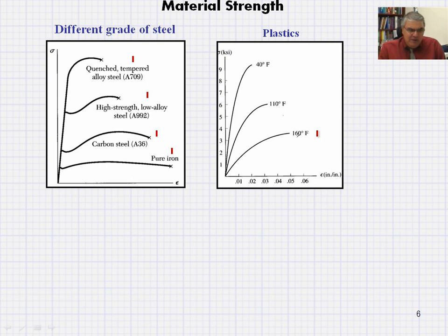So this last one down here, the strain is almost 1/3 of the one that's shown up here, but the strain is also 3 times or more. Again, that would help us with determining which material is more ductile, depending on the application that we want. We may have a design that requires a much more ductile material and less strength, and so on.